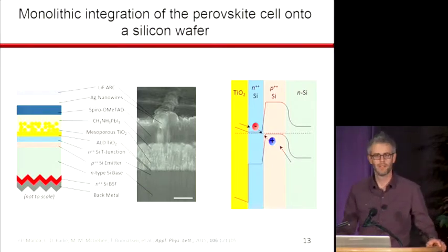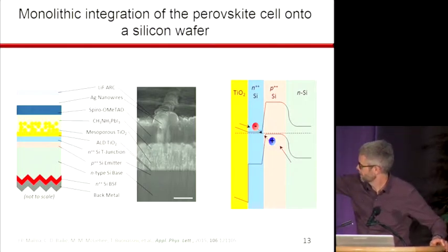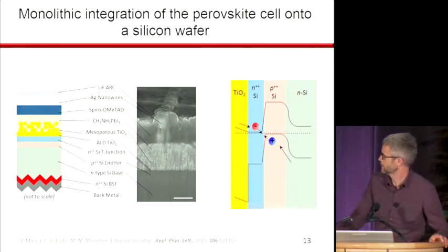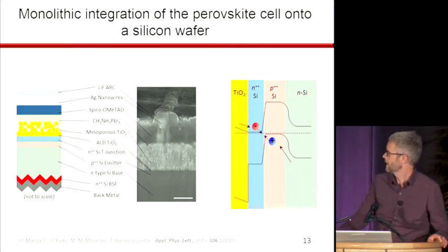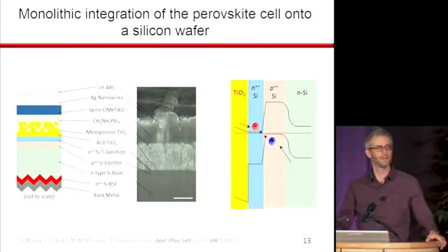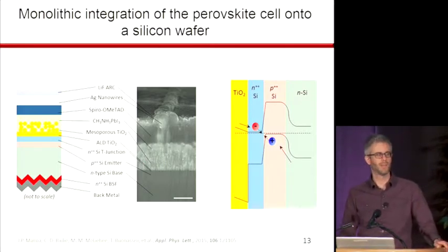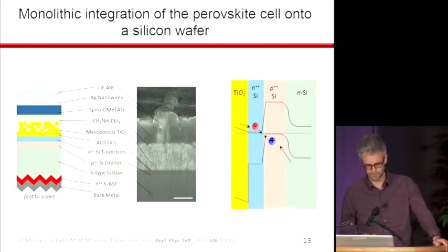We're using 470 nanometers of it, and that's because our perovskite cell is rough, and we don't want the perovskite to touch the metal electrode. So we just need to make that layer smoother and then use less of this material. And also there are other materials that would absorb less light. When we fix that, I think we'll see some pretty dramatic improvements to the efficiency.